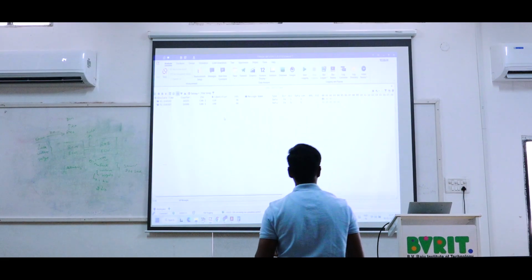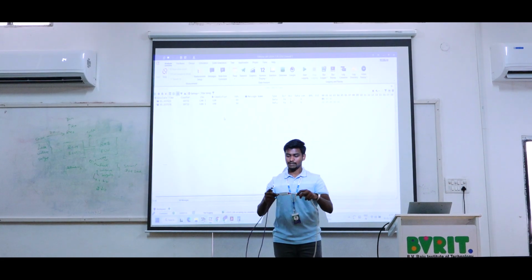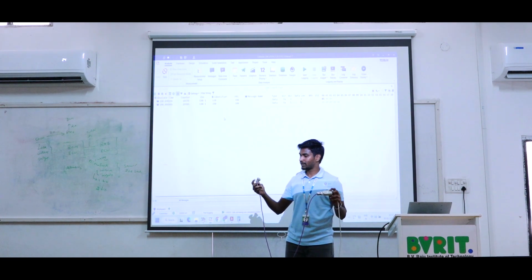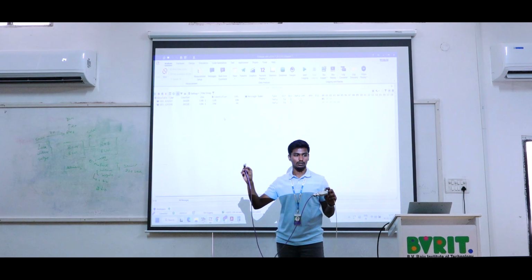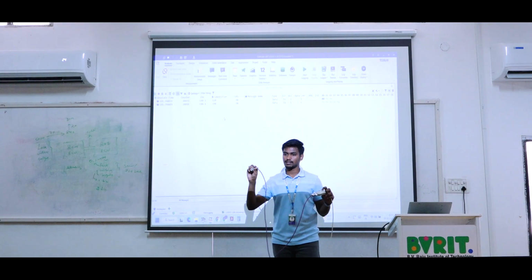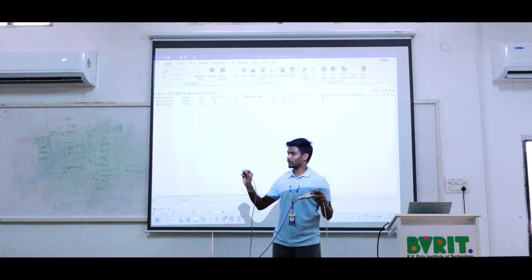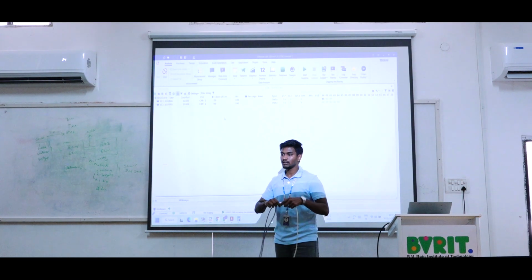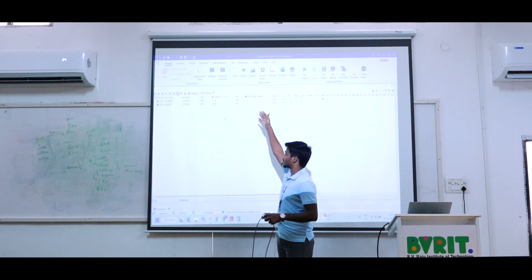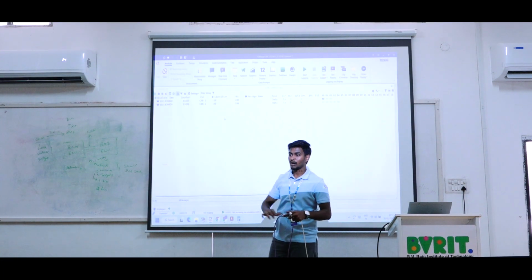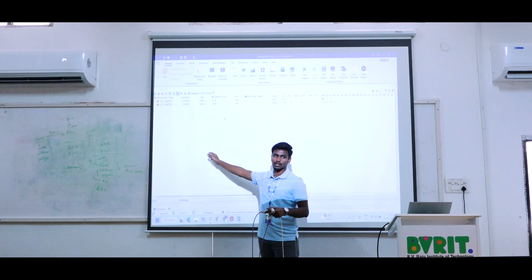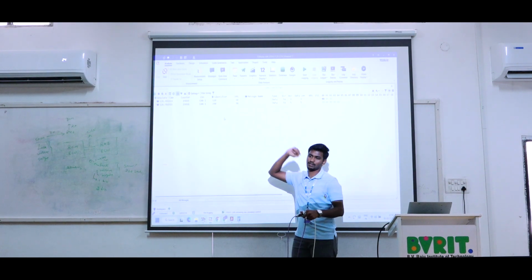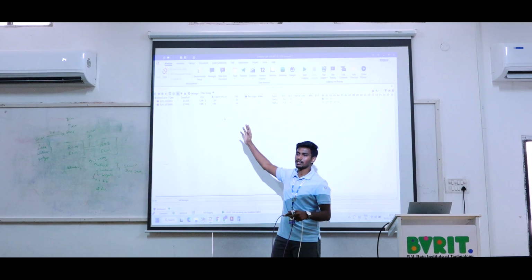If we have a real-time car, this is the CAN interface, for getting the CAN values from a car. Here now we set it up as an OBD port. But if we have a real-time OBD, we can connect this to the OBD, and on the other end we connect with our laptop. When you turn on the ignition, automatically the list of messages appears. Around 2047 messages can be created, and nearly 500 messages we are able to see here. But we don't know what the messages are.